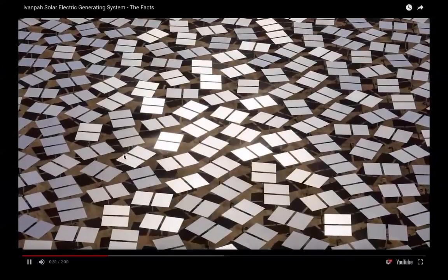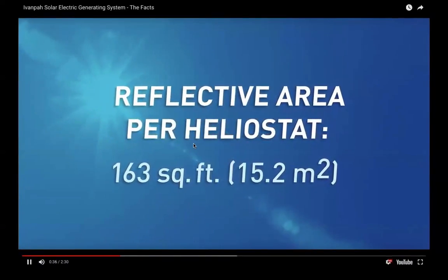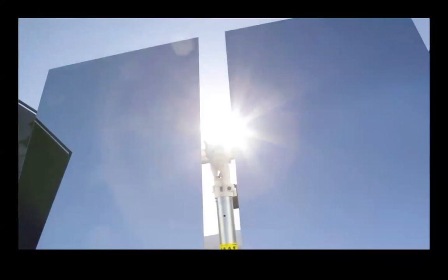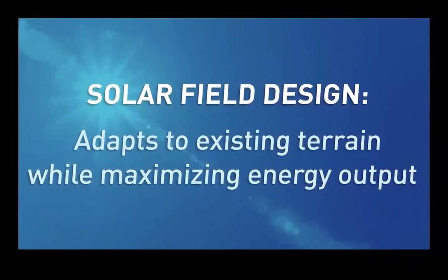Now, you see there are two mirrors for each heliostat, and there's a reason for that, obviously, because there are two axes of tracking, right? You want to use one mirror to track one side, and use the other one to track on the other axis. You can either move them separately or together, so it gives additional control.